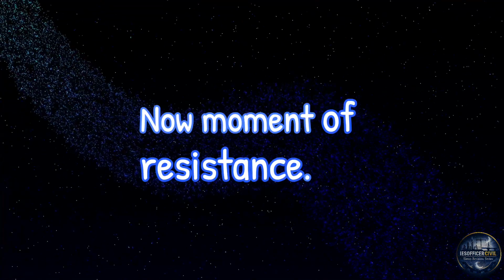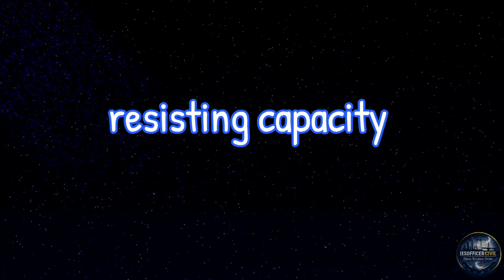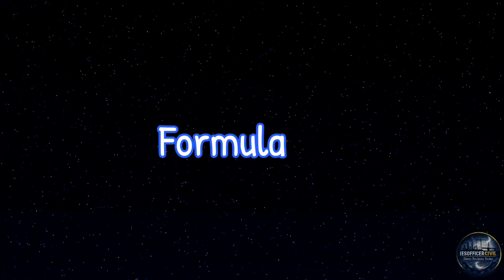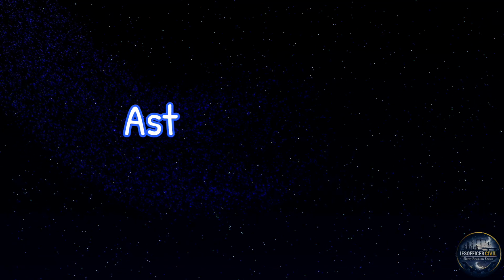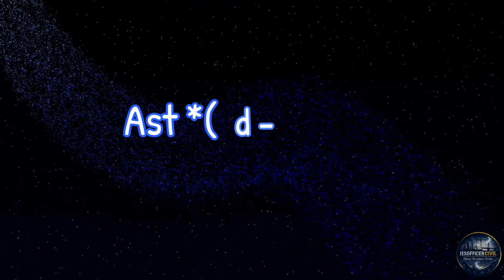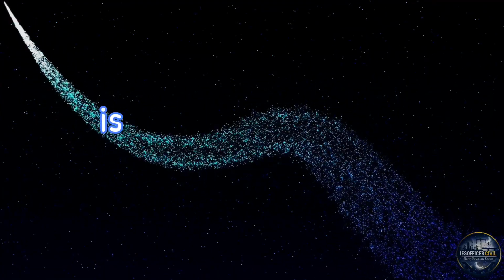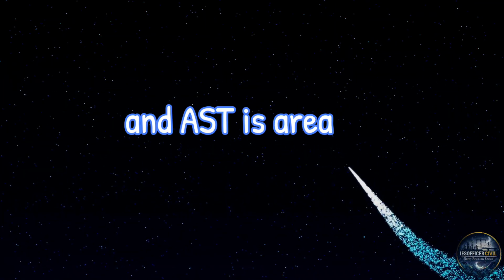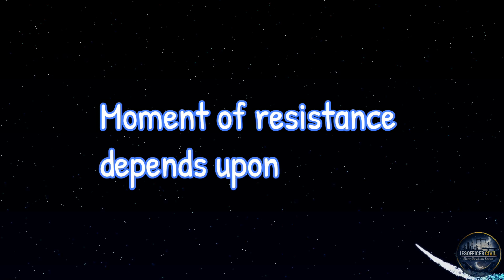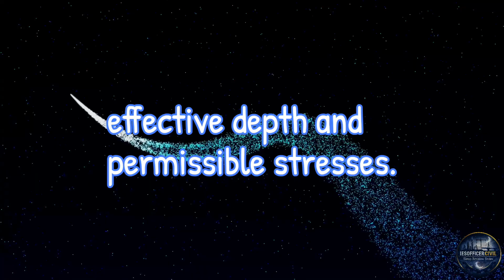Now moment of resistance. Moment of resistance means bending resisting capacity of beam. Formula: MR equals sigma st Ast multiplied by d minus x by 3, where sigma st is permissible tensile stress in steel and Ast is area of tension reinforcement. Moment of resistance depends upon steel area, effective depth, and permissible stresses.